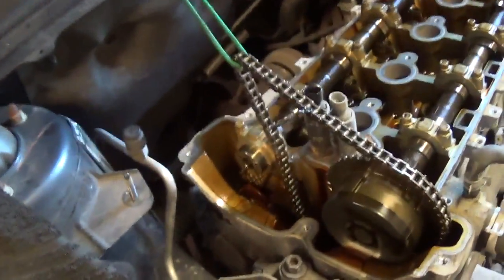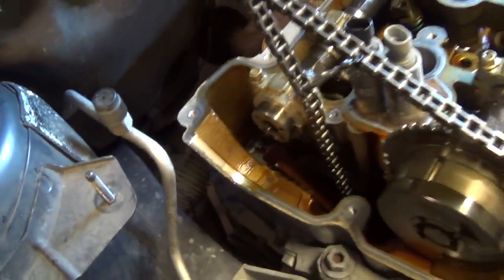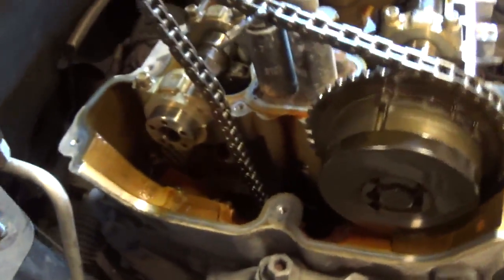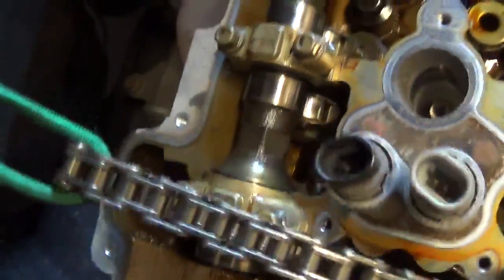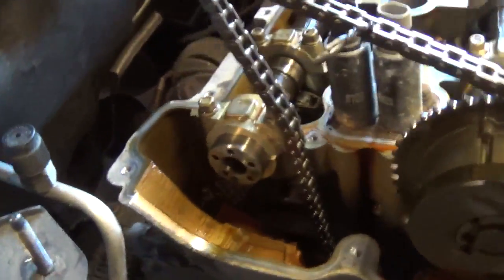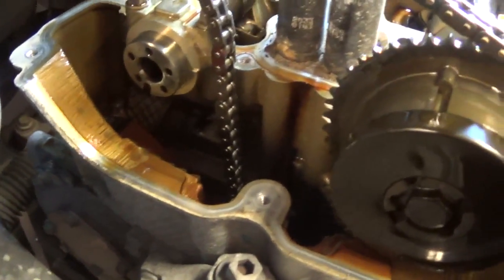Well, they don't give you enough slop in the cam chain even after removing the tensioner to just slip the camshaft out with this sprocket on there. You actually have to remove the sprocket, and there's a long bolt that goes through it, and that sucker was in there like, I don't know, 200 foot-pounds. You got to hold the camshaft there and get a breaker bar on that bolt. What is it, an 18 millimeter, and get it off. But that's what it takes.